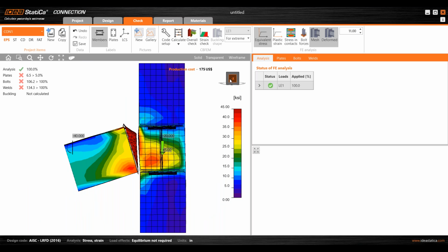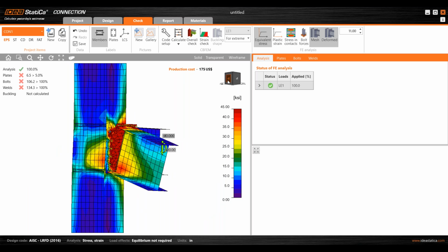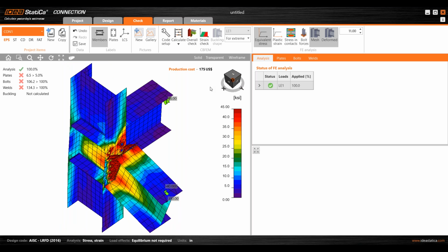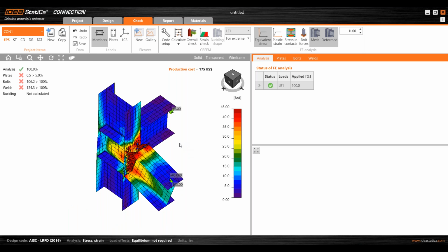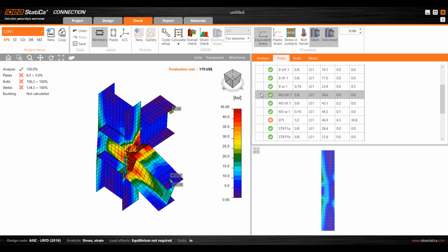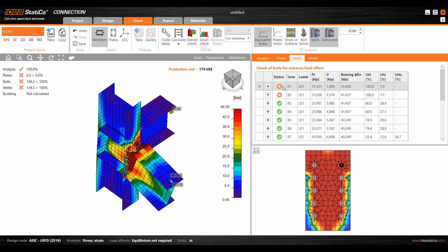So now this looks okay, right? Well, as I would expect. Then after that, the form shape is okay, as I was thinking, so I can go and check the blades, right? What is failing, as you can see here, is the end plate. Also the bolts, B1 and B2, are failing.